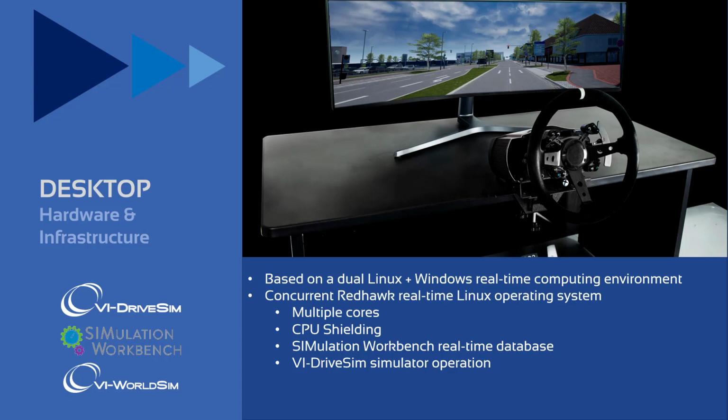This might be a primary physics model with separate high-fidelity tire models, each being solved with their own core. It may include separate control models, either through SIL or HIL, operating on dedicated cores. Each core can be CPU shielded to guarantee real-time performance without operating system interrupts. The software solution is built on top of the Concurrent simulation workbench real-time computing environment.